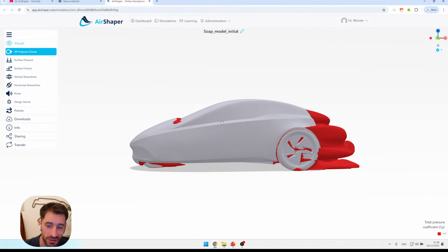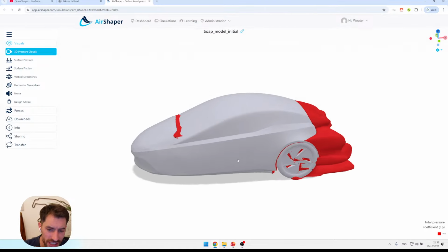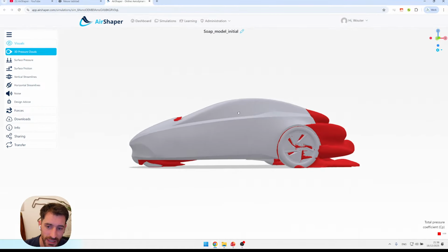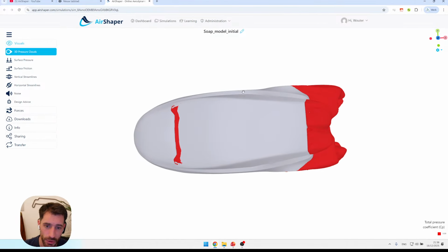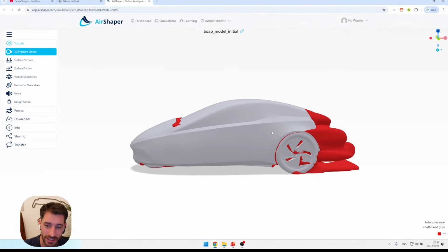So we set out to optimize the base shape, which is not an easy task. If you want to have a drop shape, which is aerodynamically very interesting, you want the widest point at the front of your car and then taper it inwards towards the rear. That's aerodynamically the most interesting shape. And here we actually had the opposite.